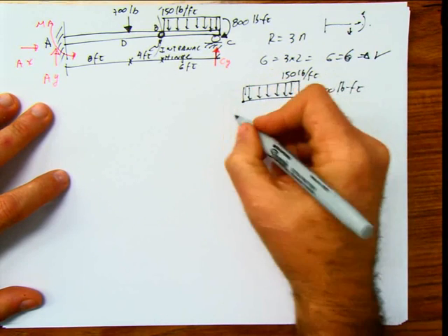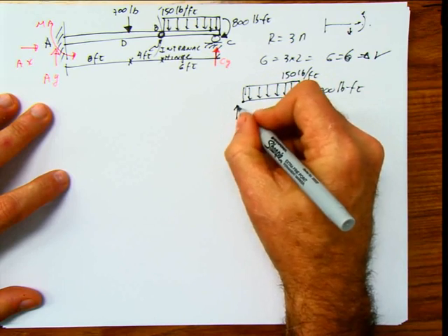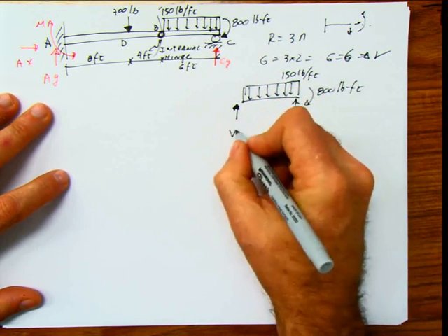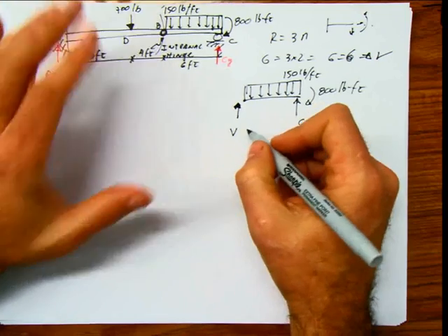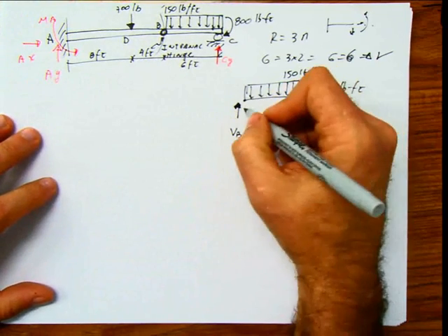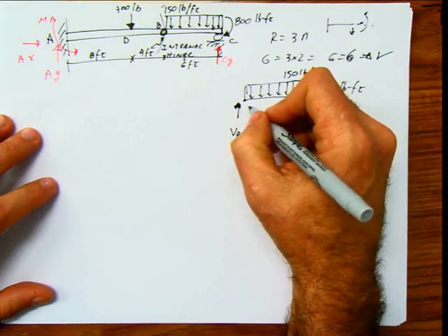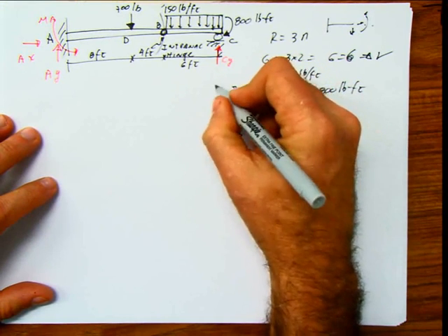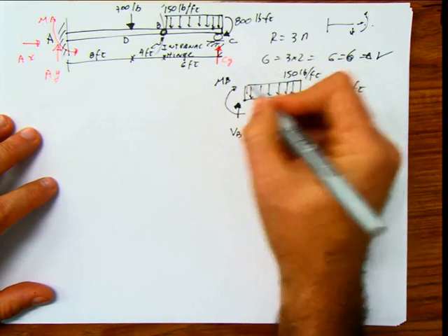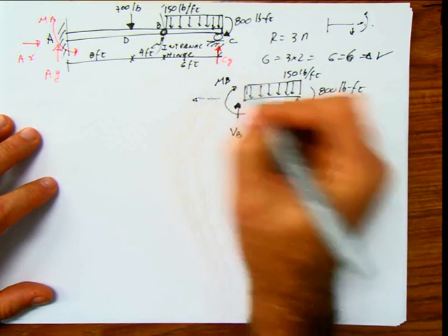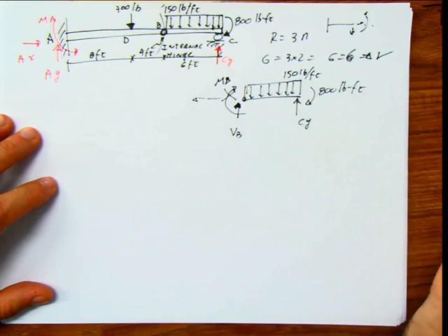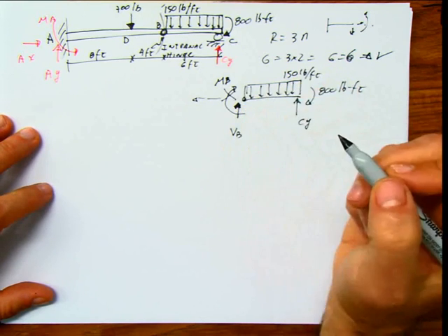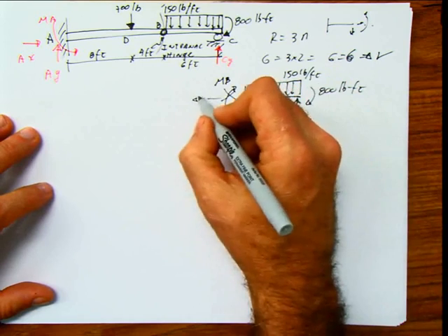And because this is a hinge, I know for sure that we will have this shear. And remember, we are using this side, that's why I'm putting the convention in this way. And we are going to have also a moment in this end, like that. And we're going to have an axial force. But because this is a hinge, I know the hinge cannot withstand any type of moment. So this moment is going to be 0. The axial is 0, but for different reasons.